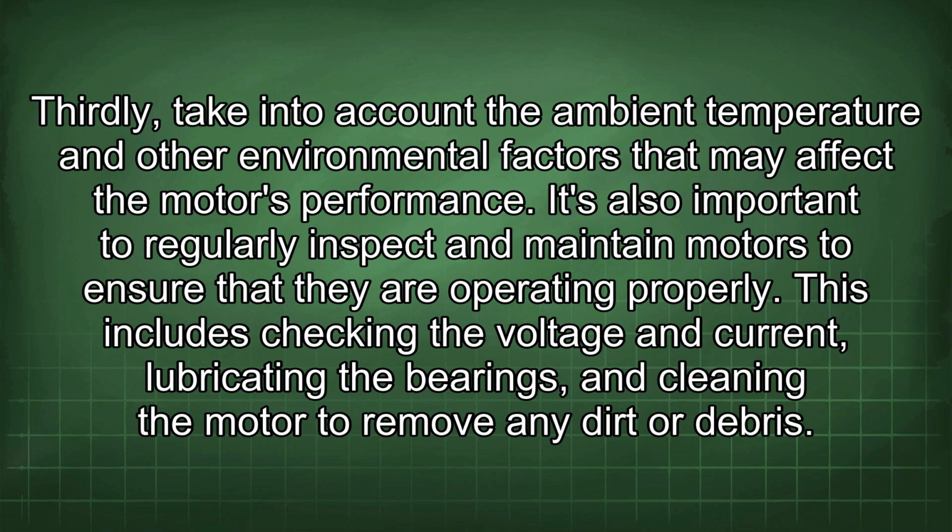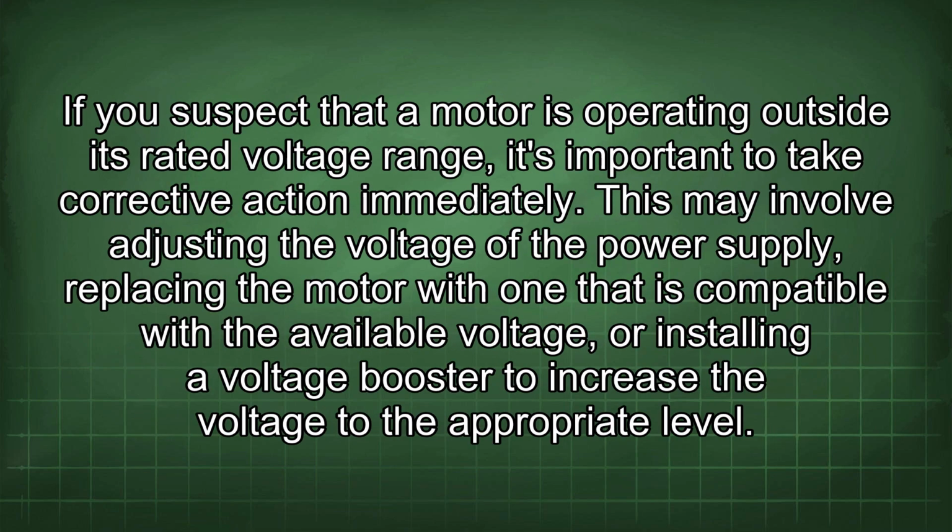It's also important to regularly inspect and maintain motors to ensure that they are operating properly. This includes checking the voltage and current, lubricating the bearings, and cleaning the motor to remove any dirt or debris. If you suspect that a motor is operating outside its rated voltage range, it's important to take corrective action immediately.